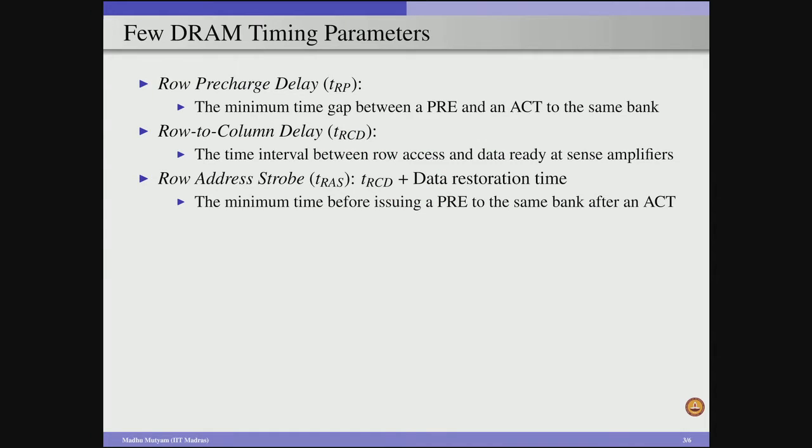Now we know that the DRAM cells are self-destructive. When I say DRAM cells are self-destructive, whenever we perform any access operation on DRAM cells, the DRAM cells cannot retain the same charge, and as a result the value represented by the DRAM cell will be inconsistent with the actual value stored in it. So in other words, whenever we perform any activation, it is our duty to ensure that data is restored properly, and this is specified by